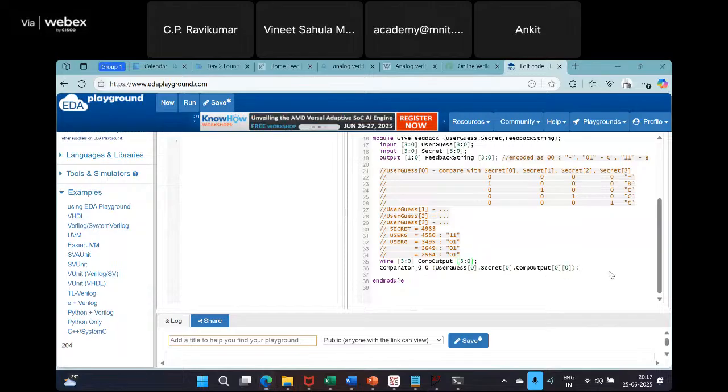Okay. So there is a way in Verilog called generate. If you don't want to write so many statements, you could say, I'll write a for loop, right? It will expand the for loop. So let us write genvar i and j. These are special variables, genvar i and j. So what we have to do is for i equal to 0, i less than 4, i equals i plus 1. For j equal to 0, j less than 4, j equals j plus 1.